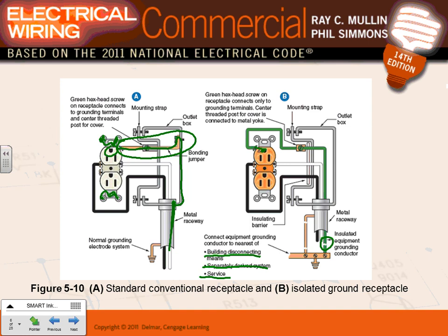One ground is ground number one. That's the clean ground. Ground number two, I'm going to put it in red here. Ground number two is the one that's going to ground the frame, that frame here, and eventually is going to ground the receptacle, the frame of the receptacle. This will be ground number two.